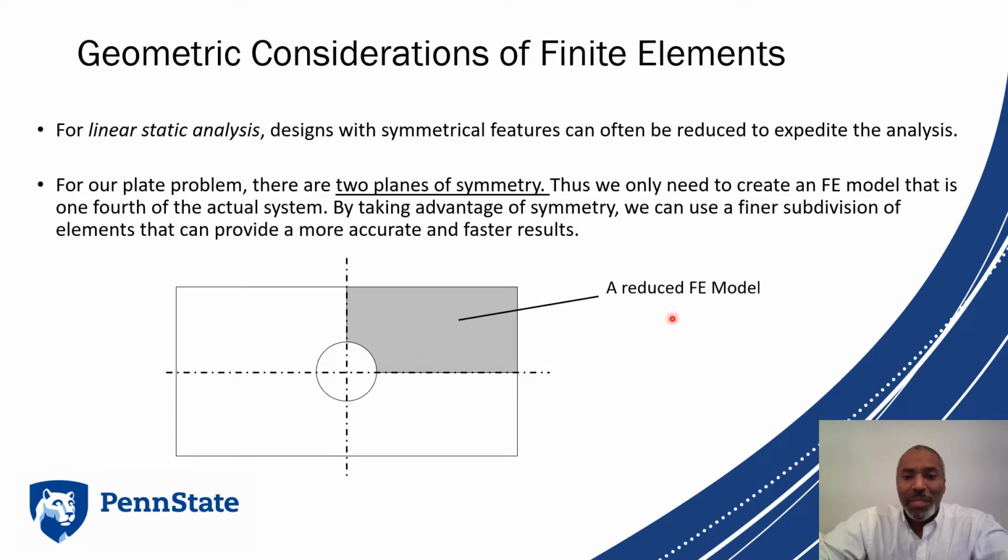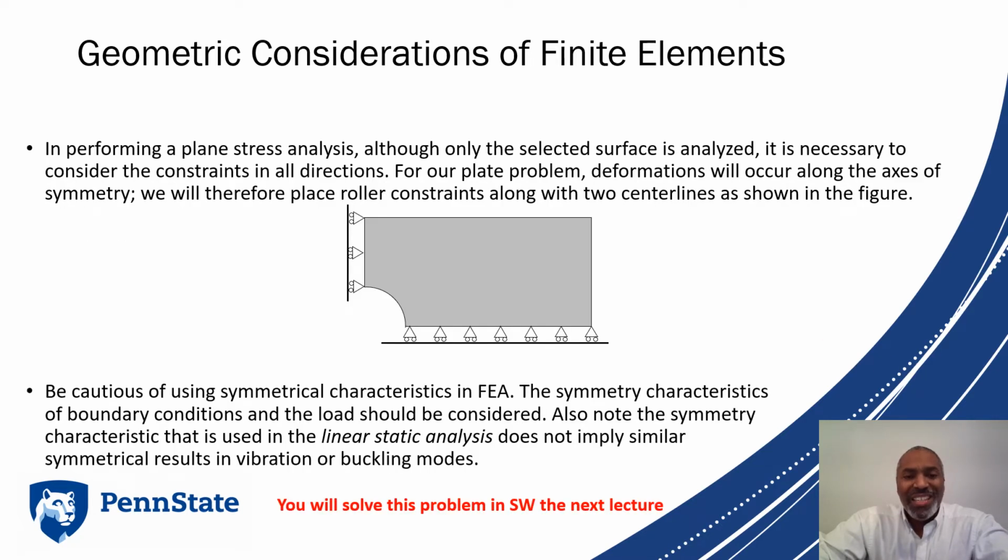How do we go about doing this? Well, if we look at the geometry of that one quadrant, we understand that the top and what would be on the bottom, and the top right and what would be on the left, should behave the same. That vertical center line should not actually move. It's just going to get pulled apart from the center. And here, the center line shouldn't move either. Whatever happens on the top happens on the bottom, such that nothing should move through this plane, and that plane therefore cannot warp at all.